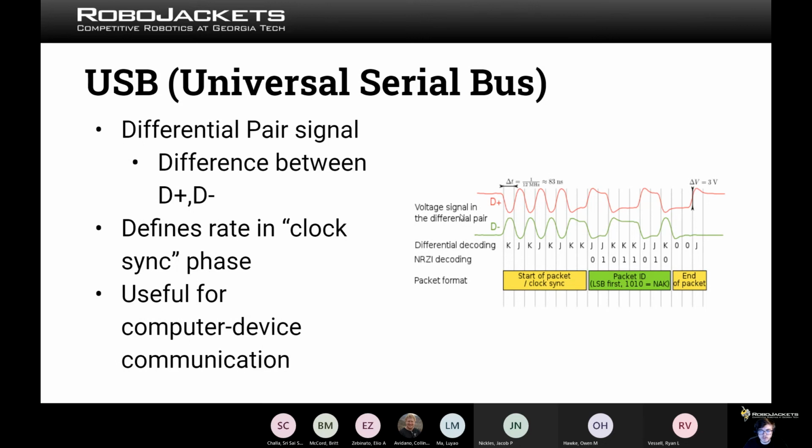So this allows for more robust signal integrity, differentially routed. For another example, Ethernet is also differentially routed, which can go hundreds of feet. But an SPI bus, or even more probably an I2C bus, won't be able to go that far in terms of length of wire or length on your PCB.